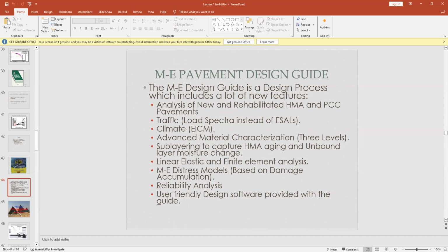Even though we have extracted most of the volatile material, there are still volatile materials that make it flexible. Believe me, if there is 0% volatile material in asphalt, it will not be flexible. It will crack itself.